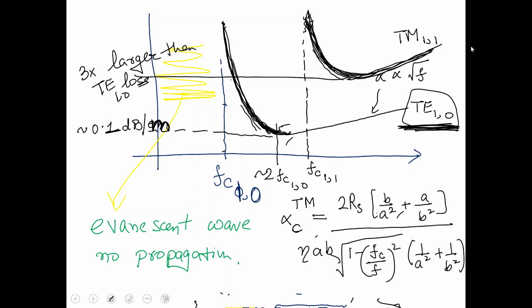In fact, the cables which are working at 2.4 gigahertz, good cables would always have gold coating on them. And those cables become expensive. Even the connectors there have gold coating. If you have SMA cables in your labs around, you can see that the connectors are gold plated to try to reduce the loss of that cable.